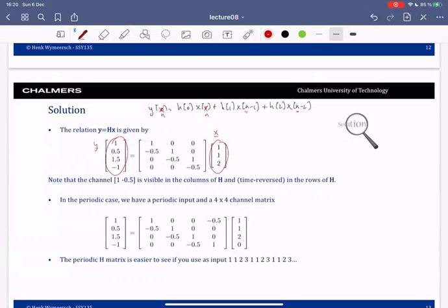And then I can rearrange the channel coefficients into this matrix. And this matrix I will call H. And you see a kind of nice structure in here where on the diagonal you have this, and then on the off diagonal you have this. And this matrix in this case will be a 4 by 3 matrix. Right, and you see the channel appearing in this column here. You can also see it appearing in this row here, in this direction or in this direction.